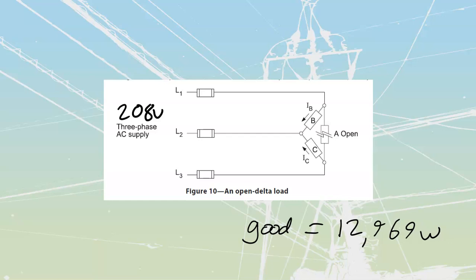All right, working with this one over here, we see that we have got 208 volts. We see that we've got 10 ohm resistances. What we're going to do is figure out our power for a single one of these. So far in this course, we've been using all of our easy cheesy values. You know, we've been calculating watts as my volts times my amps, but let's change it up a little bit here. We're going to use a different formula. Do you guys remember this one here? Watts is equal to E squared over top of R.